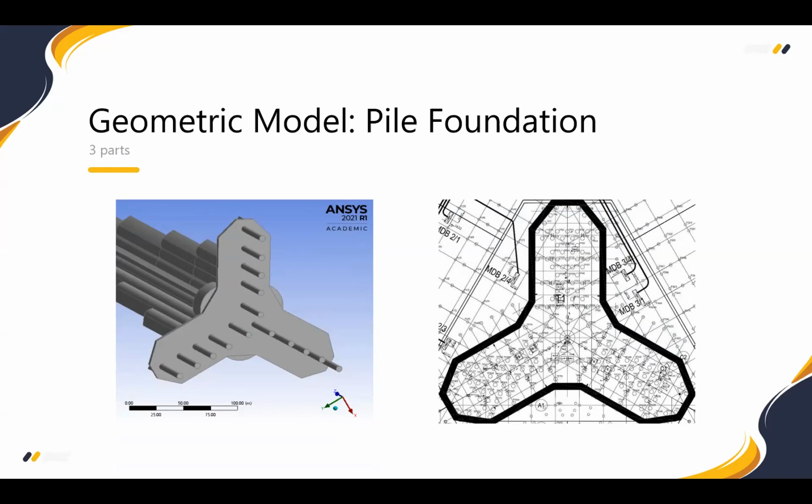To make the influence of this modification on the efficiency of the foundation as little as we can, the total cross-section area of the simplified foundation and the initial foundation are the same, and the length is also unchanged. Besides, the locations of the simplified piles are also well designed after calculation.